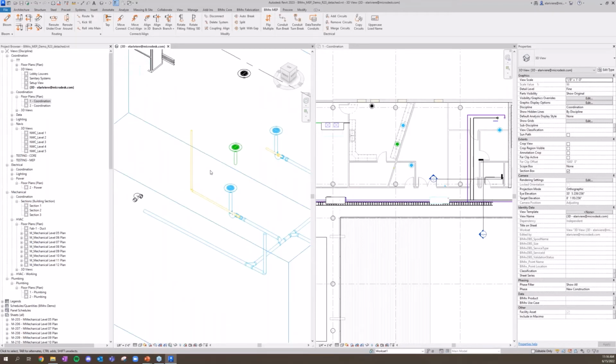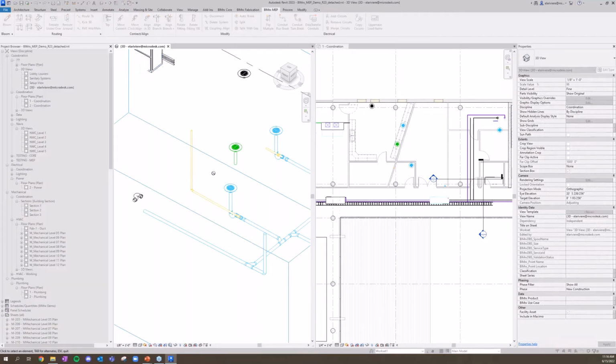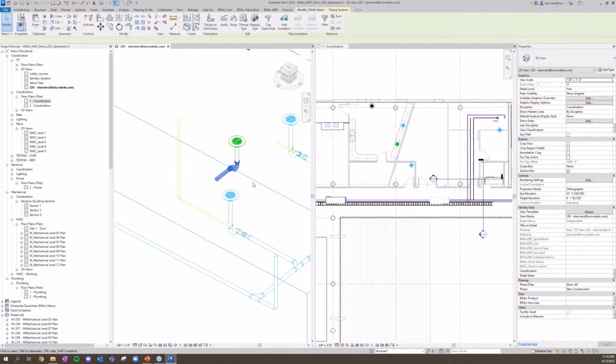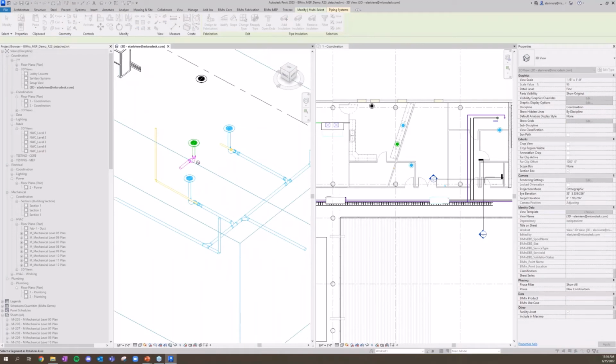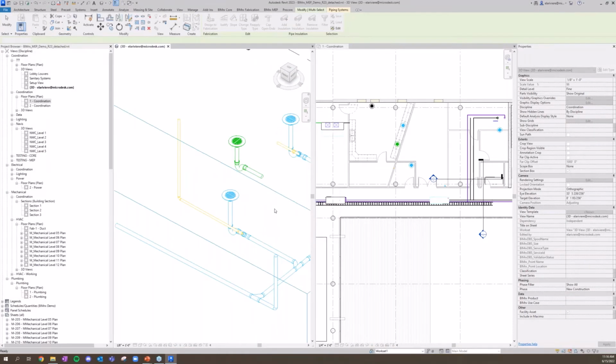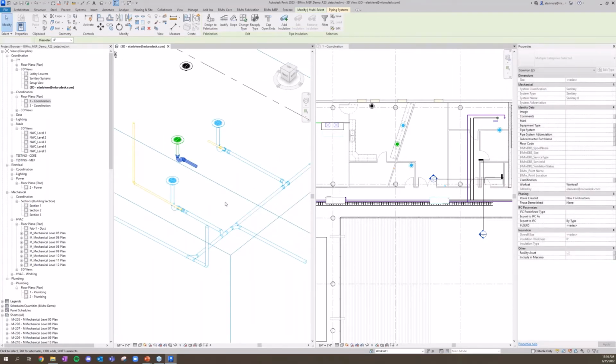And again, let's get back to that piece building, right? I've dragged a P-trap over from the side. For some reason, every P-trap is built sideways, so I can work with that. I can absolutely use move connect align to grab the closest connector, rotate and put that in the right spot. You can then bloom that element out and continue working with this one. You can grab that chunk of elements. Rather, let's grab the bottom two here and use our rotate fitting command, which allows for a pre-select. Doing that rotate fitting command allows me to rotate and aim directly at that run over there.